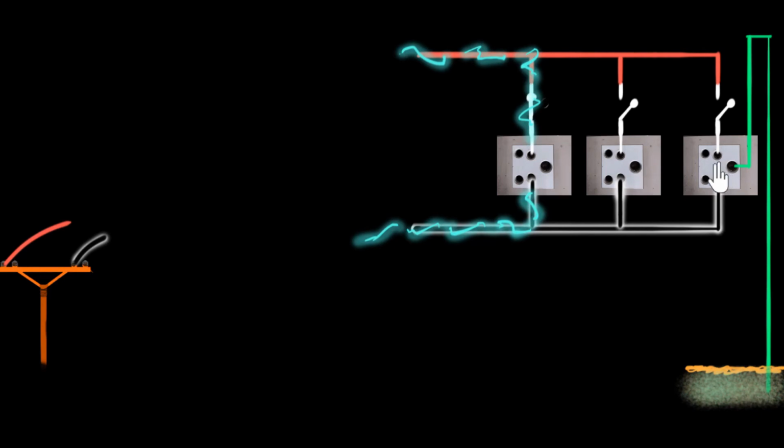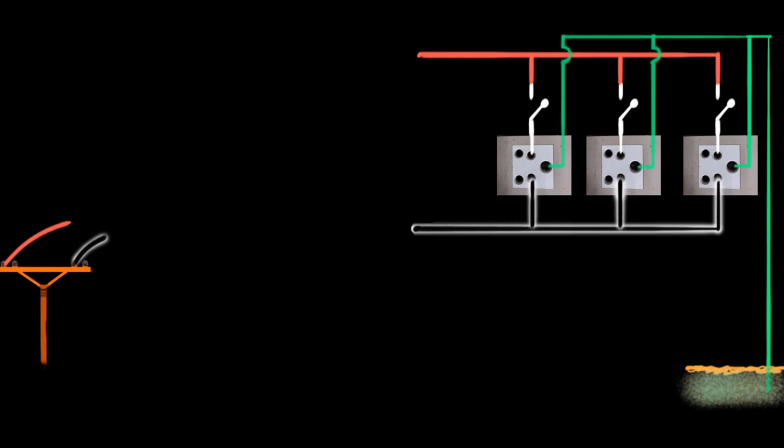It's independent of these plug points and those switches. So parallel is how all the circuits are connected in our houses. And of course, they would have their own grounds as well. That's also super important. And by the way, if you're looking at this, you're wondering what this curve means. It basically denotes that the ground and the live are not connected to each other. It's just a way of showing that they are independent wires. It shows that one wire is going above the other. That's it.